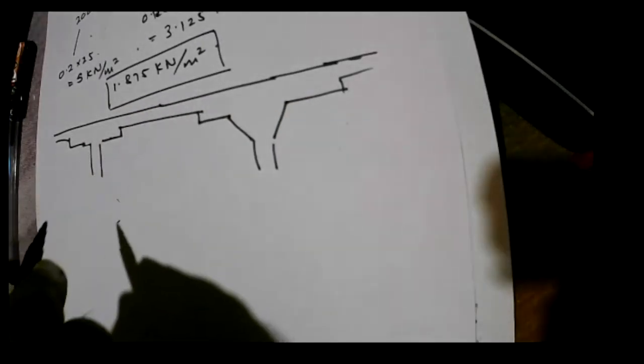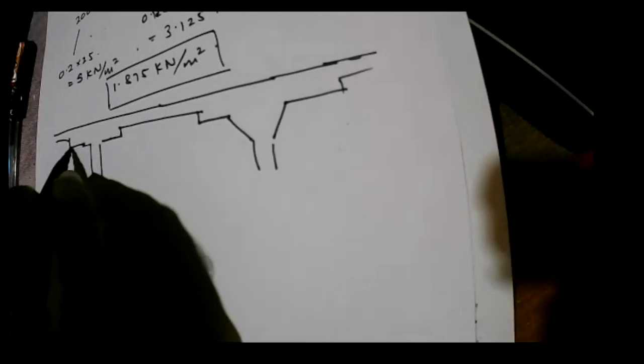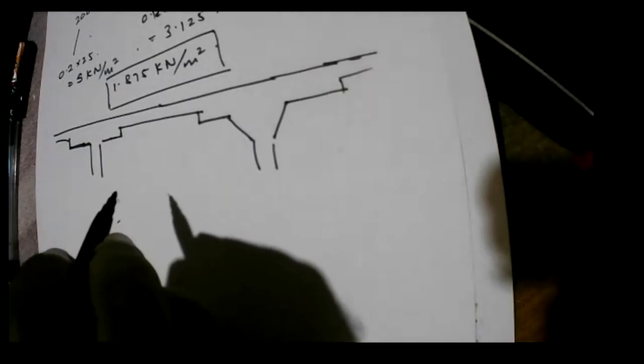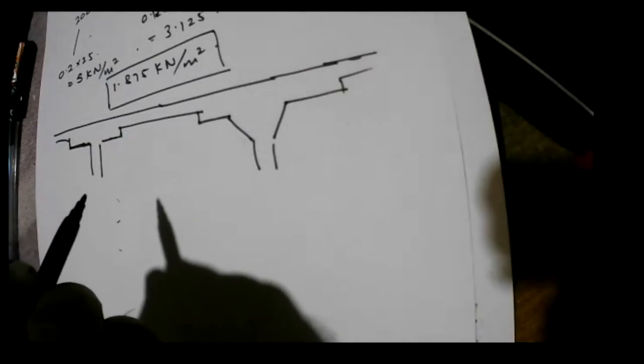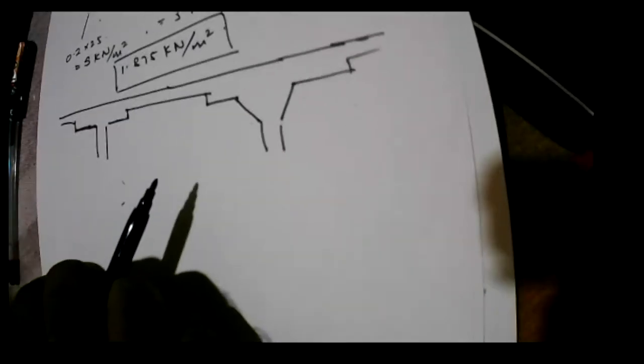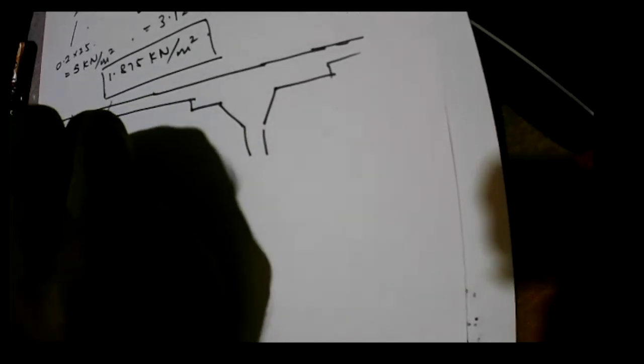But both these have a disadvantage, and that is, during the casting, you have to form all these shapes. So because of that reason, structurally this may not be very efficient. When it comes to construction wise, it may not be efficient. But when it comes to the structural behavior, this is reasonably good because we can prevent the punching shear possibility by increasing the thickness of the slab.